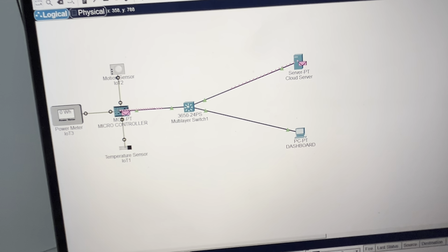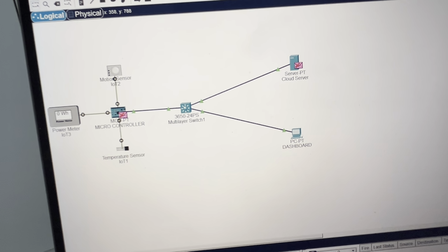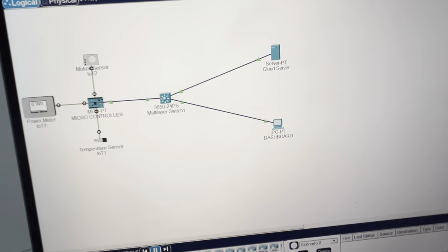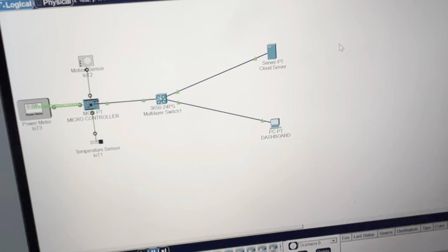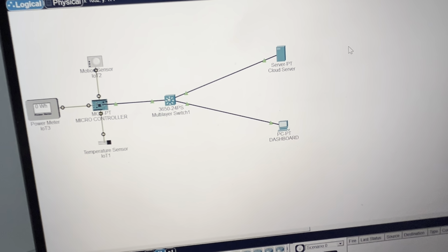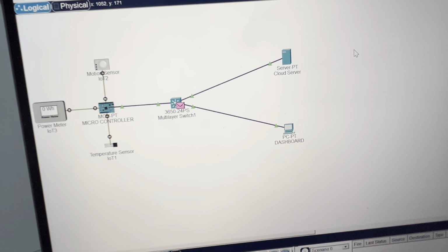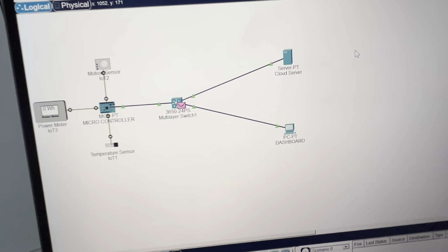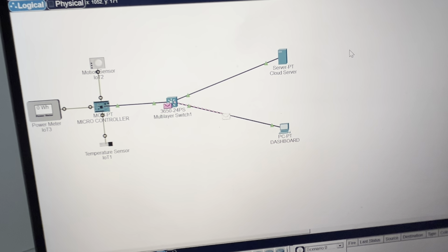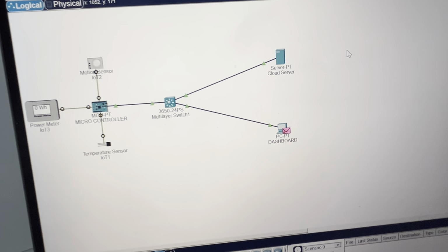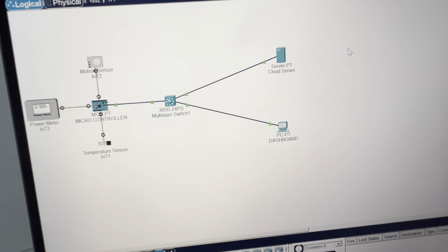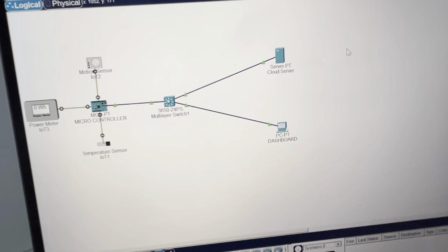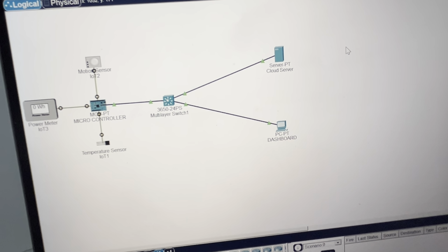Next I will demonstrate the visualization layer, which you can see is on the dashboard. This is where the monitoring of everything will be done. The processed data is displayed on a dashboard using tools such as Grafana or Power BI. On the dashboard, we can see real-time sensor readings, historical trends, and alerts for abnormal conditions. For instance, if an ATM shows abnormal vibration, the system highlights it immediately. This allows maintenance teams to take proactive action instead of waiting for a failure.